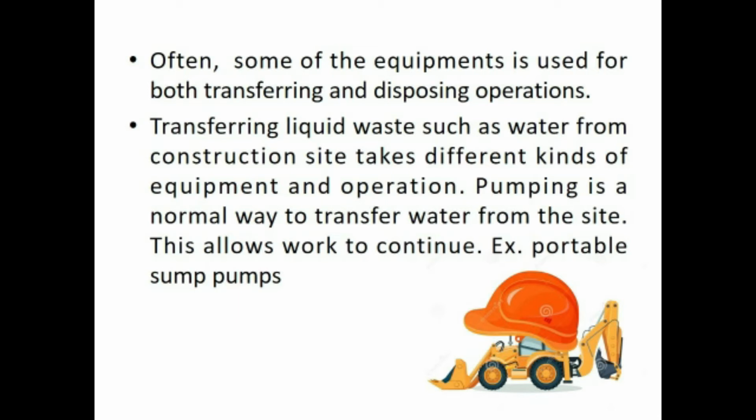Portable sump pumps, which are operated by electrical or gasoline power, are easily lowered into the excavation. The water is pumped through lengths of piping to another location away from the working area or directly into storm sewers.